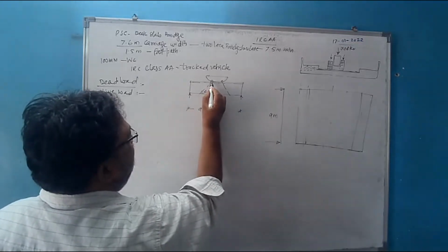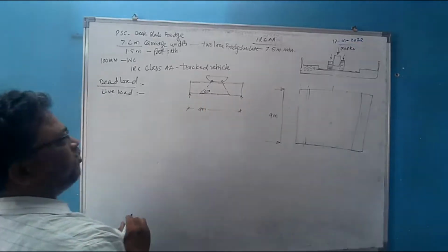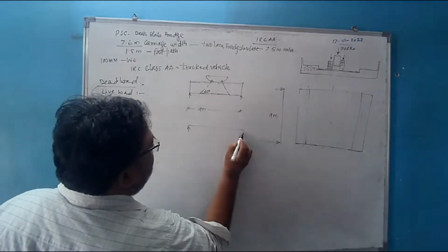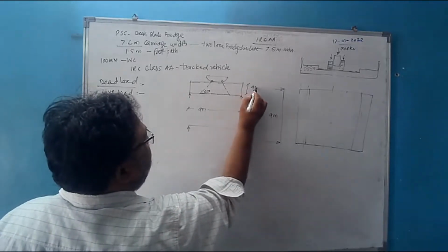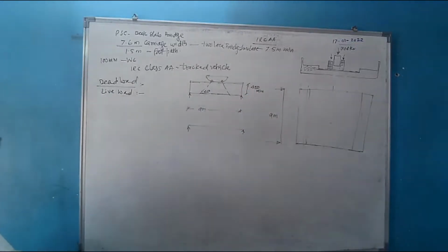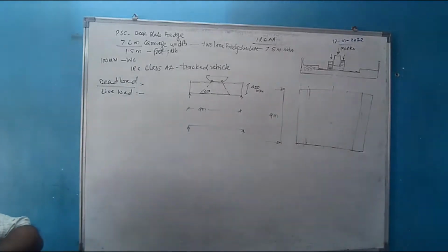So this is from the wearing coat and the deck slab. So this is the span on which the effect of that load will be. We had considered the thickness of deck slab equal to 450 mm. That was assumed. If this turns out to be unsafe then we will make the change. How had we assumed the thickness of the deck slab as 450 mm?